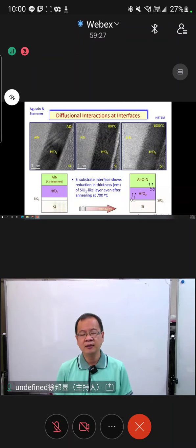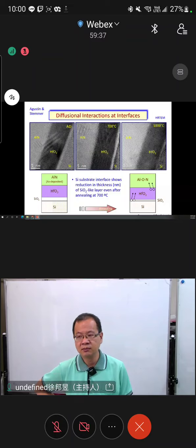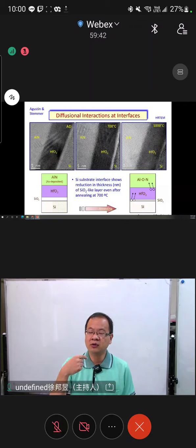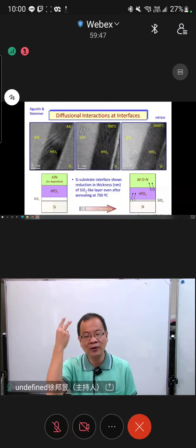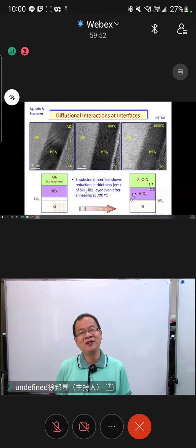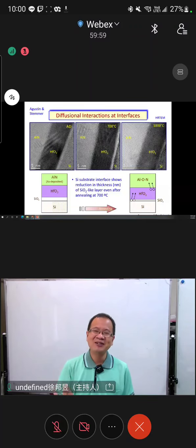However, if you calculate it, if you bias the small voltage on nanometer, your electrical field is large, right? And we have entered the 2 nano era. So 2 nano era means if you have 1 volt or 2 volt, 2 volt is very small voltage, right? 2 volt applied on 2 nanometer means the electrical field is like 10 to the 7 volt per centimeter. That's very challenging because the electrical field is so large.